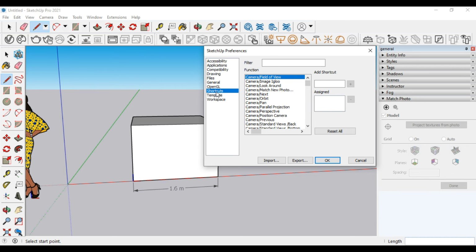So in this case, the next one is shortcuts. See here, n number of tools we are using over here. If you want to give a shortcut key for all the tools, you can, but in this SketchUp file, they have given shortcut keys only for some tools. See here, for orbit they have given O, but they have not given one for the next. So if you want to give a shortcut command key for this one, you just press Shift plus I, which I was giving over here. Shift I was given here, so it is showing Shift plus I.